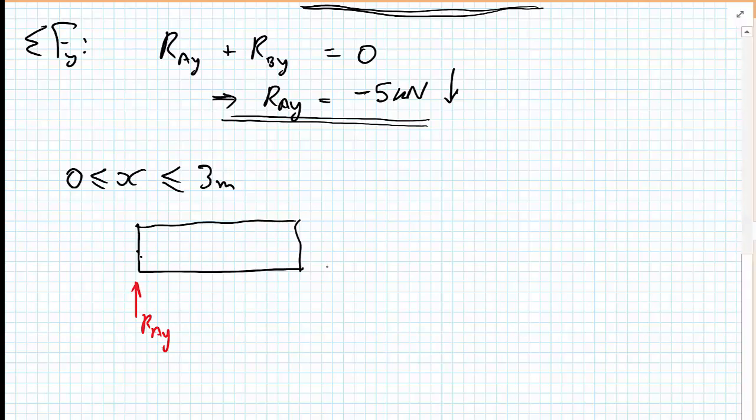At the cut, at position x, if I'm going with the shear force rule up on the left, down on the right, I can write my shear force Vx down on the right, and I draw my bending moment anti-clockwise to give myself this kind of deformation to be positive. Finally, for the free body diagram, the last thing to always put on there is the coordinate itself, x.